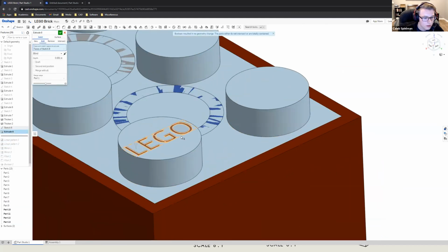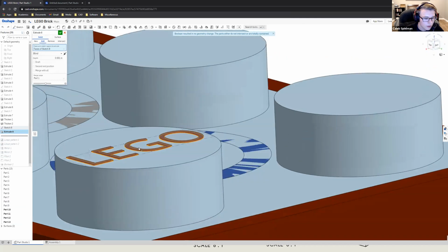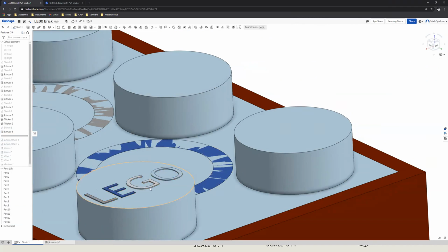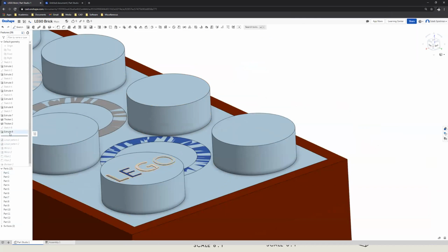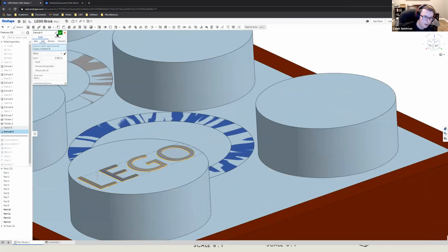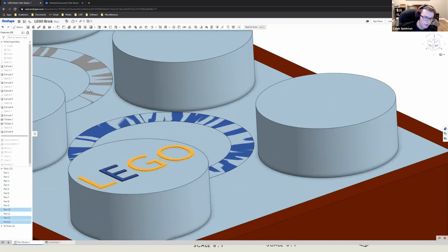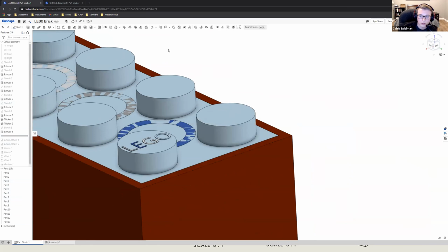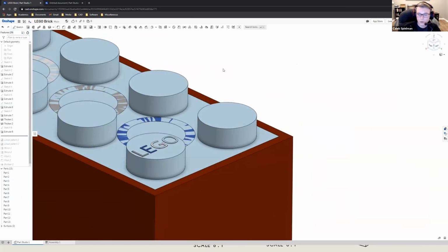So here's my extrude. As you can see here, there's the sketch. With this solid, there are several options that you can do. In the case of what we want to do here, we could do new. And that will make them all separate from the main body. Okay, I see. Just to demonstrate, if I did add instead, they would, oh, hold on, give me a minute. Yeah, I can select them now. Oh, I have a different feature driving that Boolean operation. All right, so if you click add, it would merge.